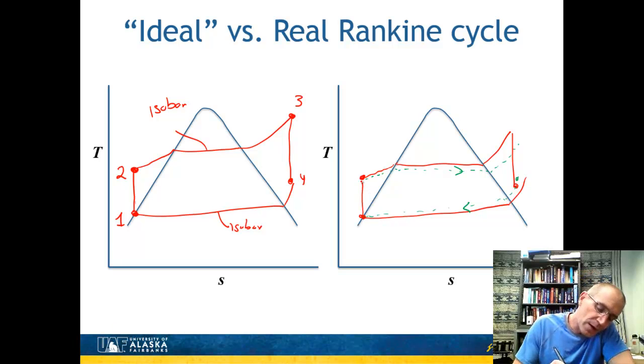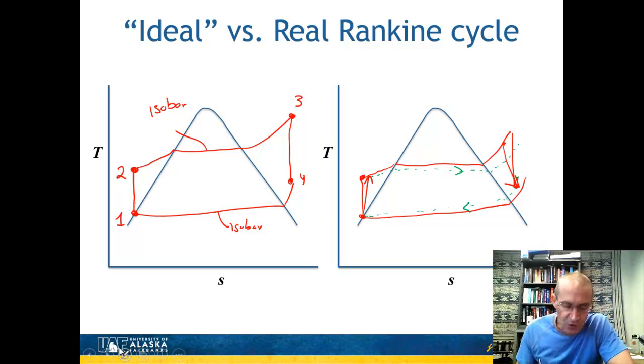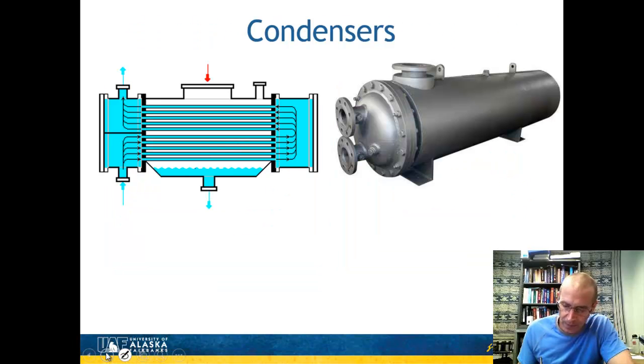And another thing is that, as we just mentioned with the ideal, these are vertical. You could have an efficiency where these would actually be sloped up and to the right, and then this might go down and to the right. And so in the ideal cycle, we have those tilted. And this we can calculate. This would be for the isentropic efficiencies of pumps and turbines, so that we can actually solve for it in the realm of thermodynamics.